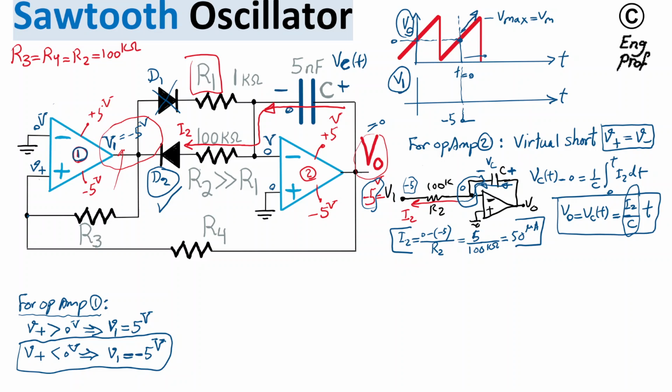So as Vout is increasing from 0 volt onward, the moment it gets close to 5 volt, which is the maximum positive saturation voltage, because R3 is 100K and R4 is 100K, and on one side we have V1 connected to R3, and on the other side we have R4 connected to Vout, which is increasing toward 5 volt finally.